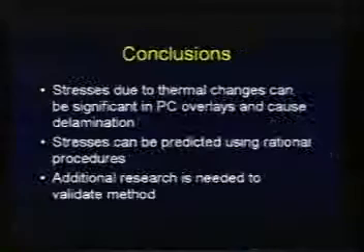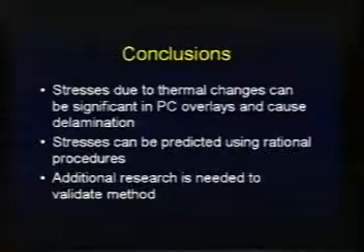But I think it's clear that stresses due to thermal changes can be very significant in placing two materials together in which the coefficients of thermal expansion are different. But I think it is possible to predict what these stresses are using rational procedures. But I think we also need to have some additional research to validate the method. Be glad to answer any questions.